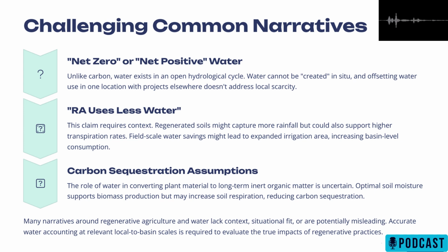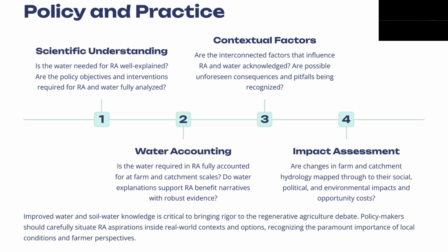This could mean less need for supplemental irrigation and rain-fed systems, or more efficient use of irrigation water when it is applied. So potentially less water needed from external sources. Okay, argument for more. Well, degraded soils might actually need more frequent, less efficient irrigation just to keep crops alive. And counterintuitively, perhaps, a really healthy, well-watered, regenerated soil supporting vigorous plant growth might actually transpire more water overall than a struggling crop on poor soil. More biomass often means more water use. And then there's that paradox of efficiency again.